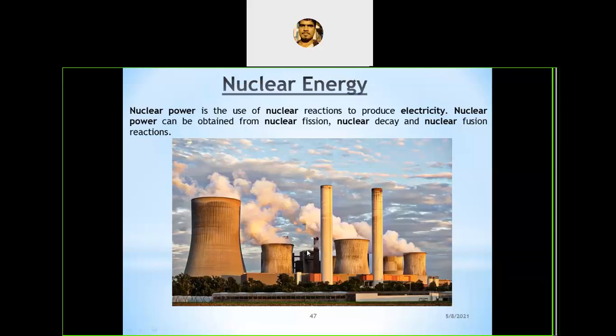And in India, the ore is poor in uranium content. Whatever ore is obtained has a poor uranium content, 0.025 to 0.067 percent. A 235 megawatt plant requires about 23 tons of uranium besides an initial charge of 60 tons. So if you want to generate 235 megawatts, it needs 23 tons of uranium besides the initial charge of 60 tons.